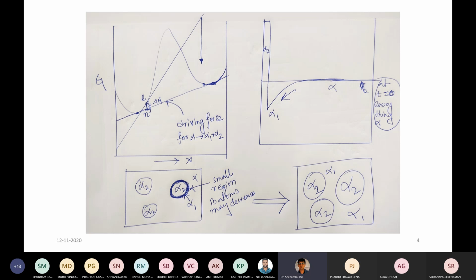You can see that from the previous slide discussion, how the P double dot tangent has a lower free energy composition existing, because below the tangent a significant portion of the Gibbs free energy curve exists. So the compositions of phases in two phase regions are given by the tangent points, and the amount of each phase is determined by the lever rule. That is also important, and based on that you can find the composition of the individual phases.